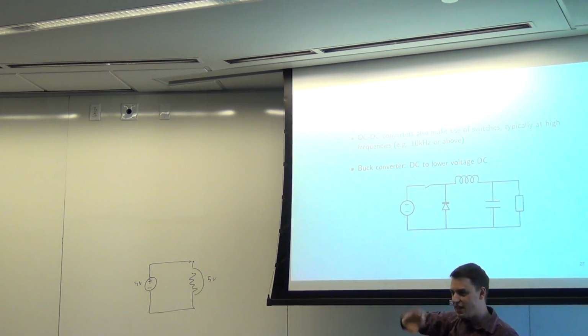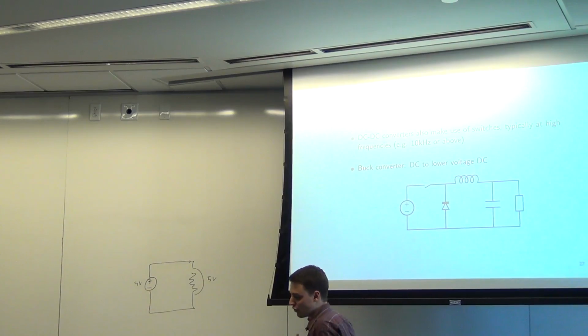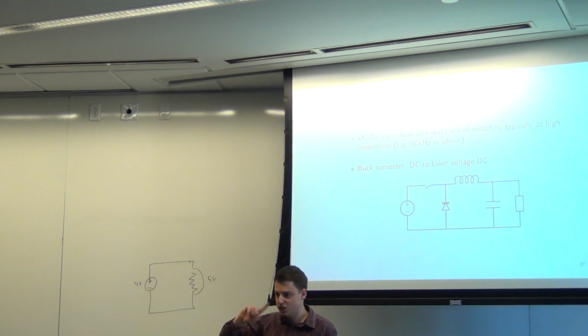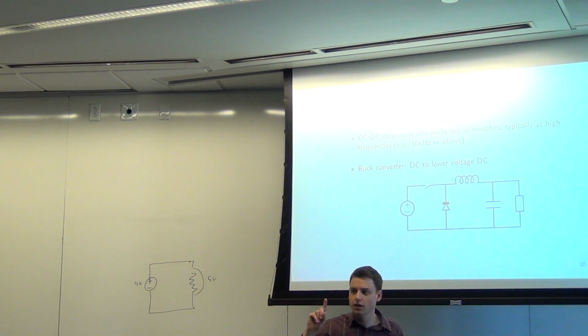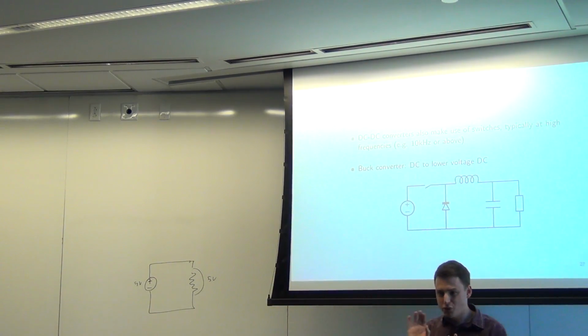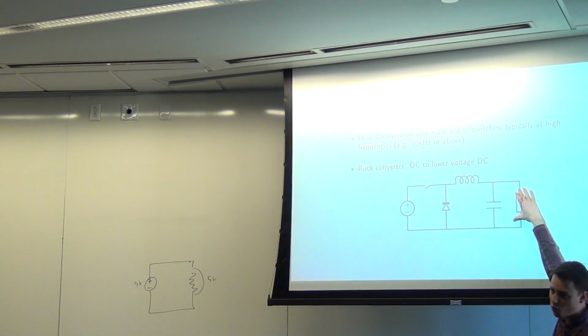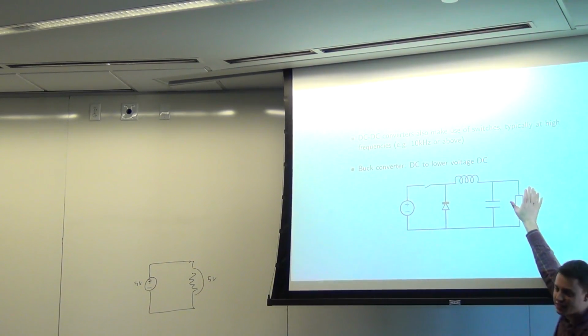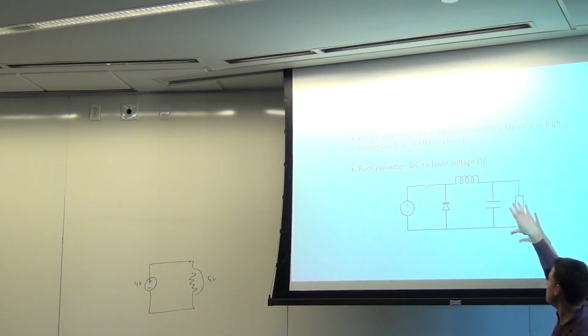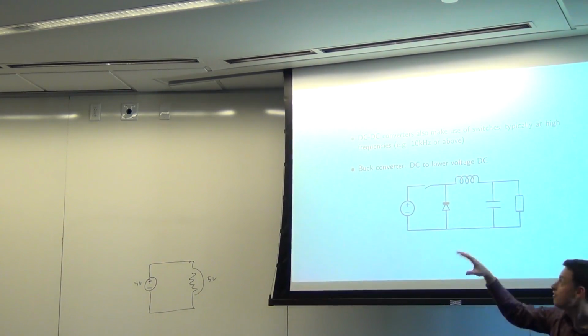And the idea of a buck converter is that if you switch that switch very, very fast, it'll be in between those two. And you'll see actually a lower voltage across this thing. Now, importantly, there's no loss here. So when you see a lower voltage, that means you have to have a higher current flowing through this.